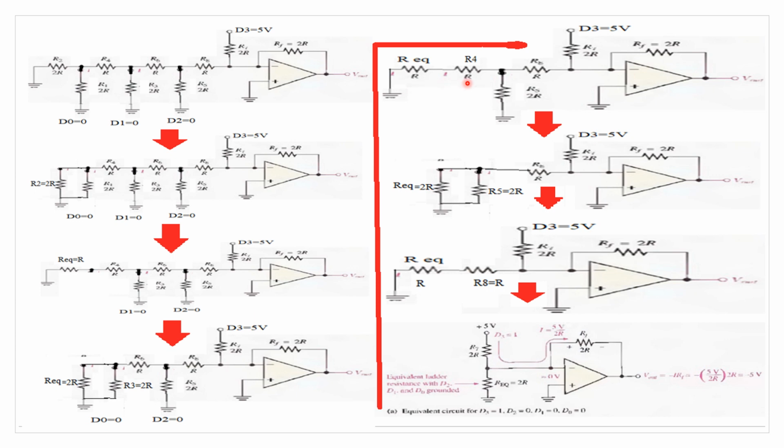Now these two resistors are in series, hence the effective value will be R plus R equal to 2R. That 2R will be parallel to this 2R. The effective value will be R, that is in series with this R. Hence the equivalent value will be R plus R, that is equal to 2R.